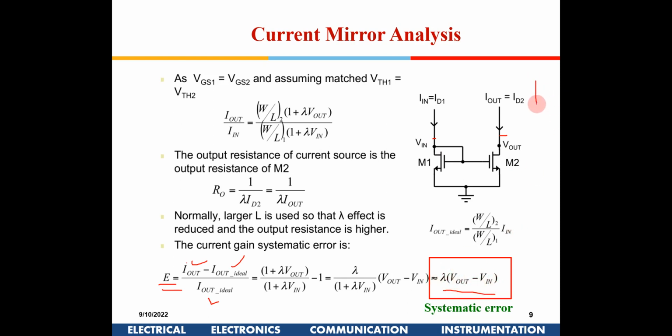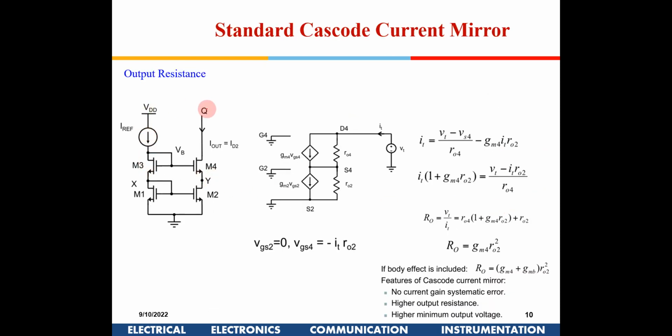Now also in the small signal analysis, when you look from the top, I will have an R0 here. In the small signal analysis, this is providing R0, the output resistance of this is R0. So these are the two issues with this particular design. Then we thought of an improved design where we connected like this.